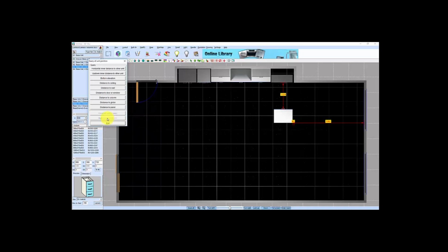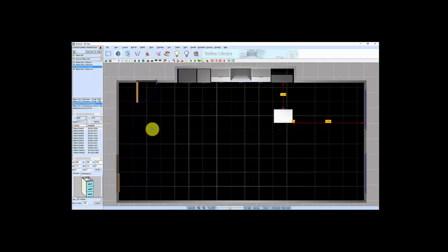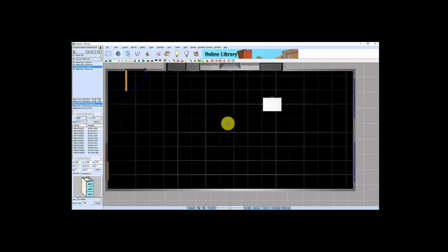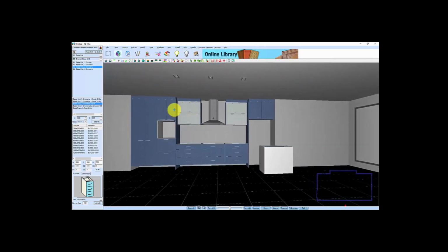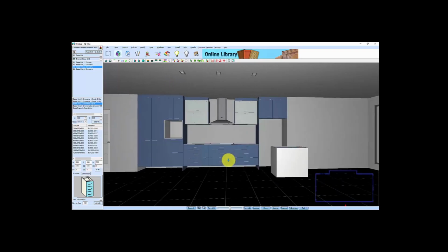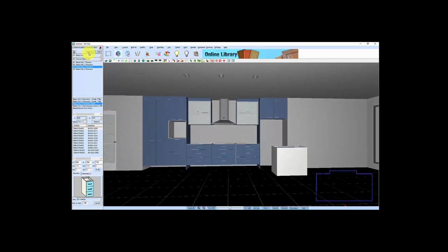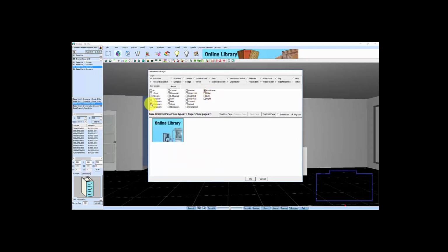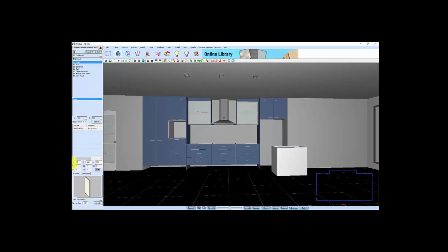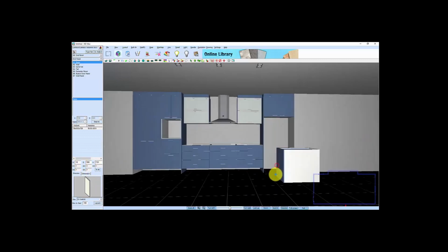What we'll do then is I will then go exit. From there we can now start placing our other cabinets. So what we do is we'll go back to our original view, which is our 3D view. So you press the world over the top there, and what that does, it takes you back to this view here. So from here, what I'm going to do is press type select, and I'm going to create a dishwasher space. Decorative panel, go OK, press 16 mil, 580 deep, 720 high. I'm going to press layout, bring that over and place that onto the cupboard there.